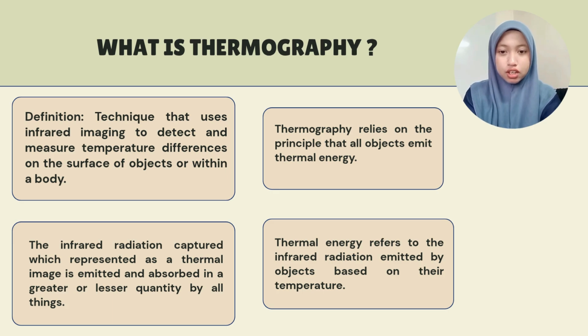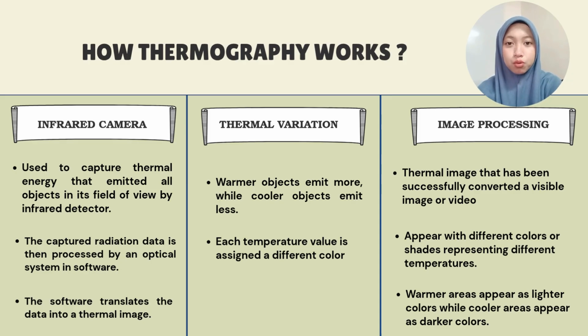What is thermography? Thermography is a technique that uses infrared imaging to detect and measure temperature differences on the surface of objects or within a body. Thermography relies on the principle that all objects emit thermal energy. Thermal energy refers to the infrared radiation emitted by the object based on its temperature. The infrared radiation captured, which is represented as a thermal image, is emitted and absorbed in a greater or lesser quantity by all things. So how does thermography work?